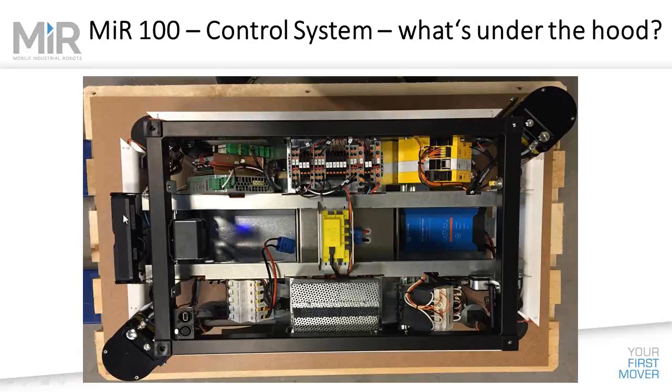This device here is a 3D Kinect camera that helps it visualize objects that are not at the 20-centimeter positional plane off of the floor. That's the plane that the laser scanners operate at. So it's seeing ankles and stanchions for machines and whatever is at that height. But as it's moving forward, it's got the 3D camera to help look for other obstructions.